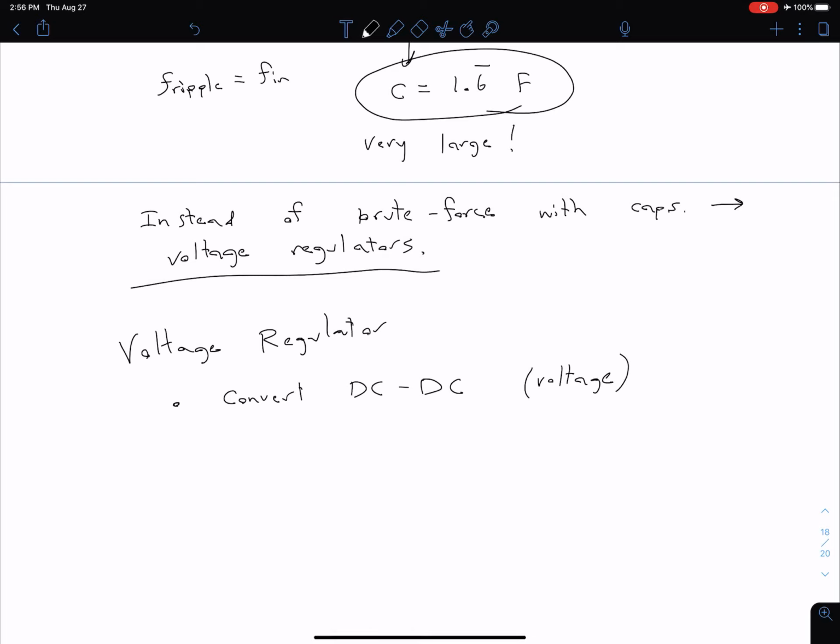And so we're actually going to see different types. You notice in the notes it says to a lower voltage, but we're going to be looking at different types of regulators. For certain types it is to a lower voltage, but for other types it can step it up to a higher voltage as well. And typically our voltage regulators are going to be improving both our line and load regulation. So typically we're improving our Δline and our Δload.